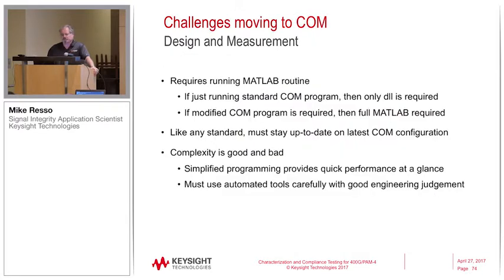So what are the challenges, right? All new characterization techniques have challenges that we overcome as engineers, but it's nice to know what they are ahead of time if you can plan for it. You do have to run a MATLAB routine. If you're using a standardized program like Physical Layer Test System that will call MATLAB, if you use that environment and wrapper, then you can run that MATLAB code simply with the DLL that's provided with the PLTS license and installation software.